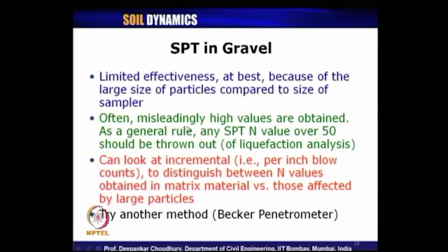Often misleadingly high values are obtained, and what is the general rule? If the recorded SPT N value is more than 50, then most of the time we need not carry out the liquefaction analysis, because we assume that the soil is not going to liquefy if the SPT N value recorded is more than 50 for plenty of repetitive tests.